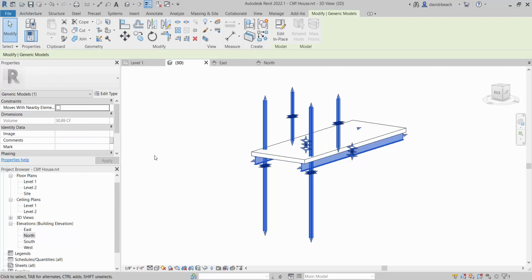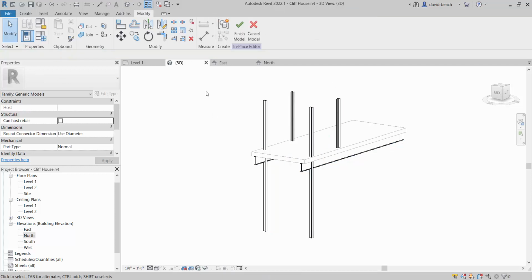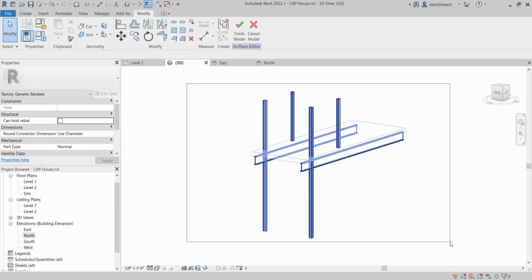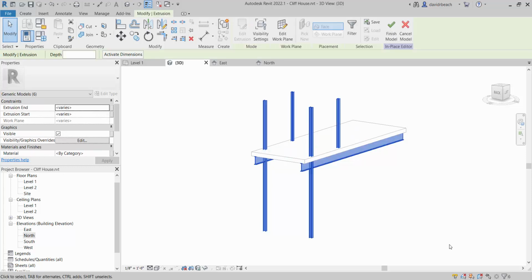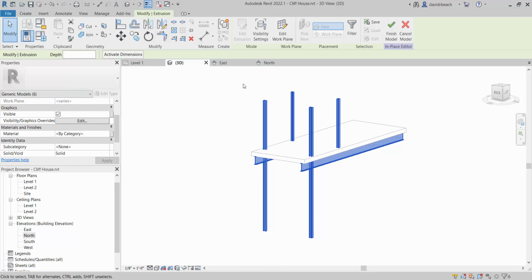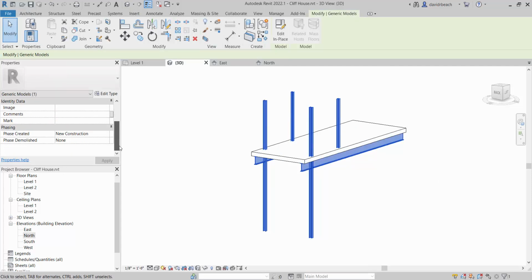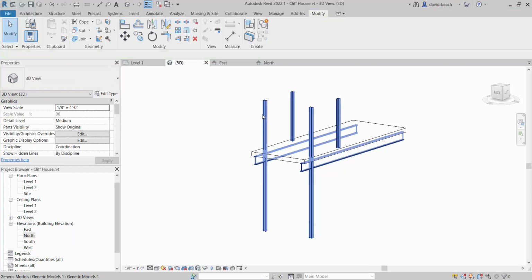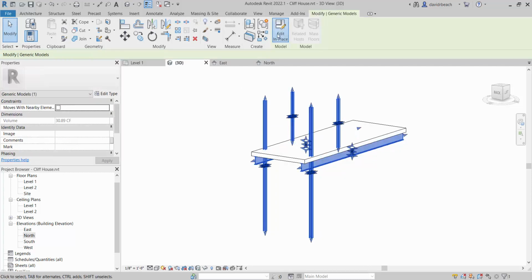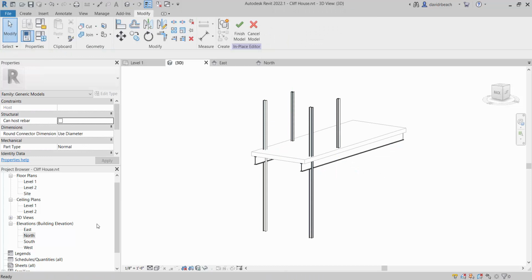So I'm going to select that family again. I'm going to go to Edit in Place, and I'm going to select all of them. So one big lasso around everybody. So that means this Properties panel is now the property for all of that geometry. If I am not in the family editor, that data will not show up over here. So I have to select it and hit Edit in Place first. I have to be editing my family for the materials to show up.